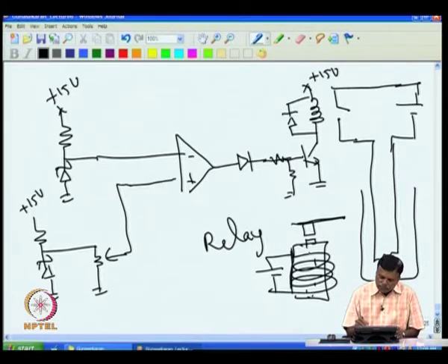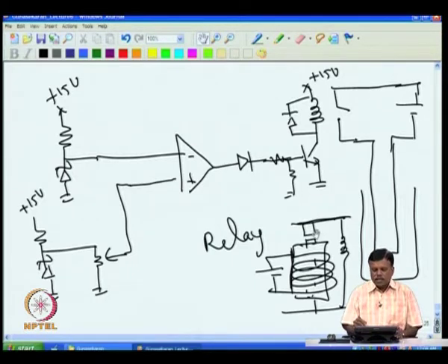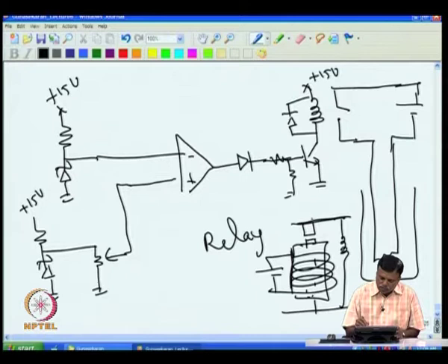Whenever current is flowing, the core gets magnetized and pulls this strip, and when no current is flowing, it does not magnetize and does not pull. So they attach a spring to this and fix it here. When current flows, the magnetic field attracts this, and when no current flows, it releases. Like this we can make a mechanical movement, and attach with insulation various other contacts that we need. If this is pulled, it will make contact, otherwise it will not.